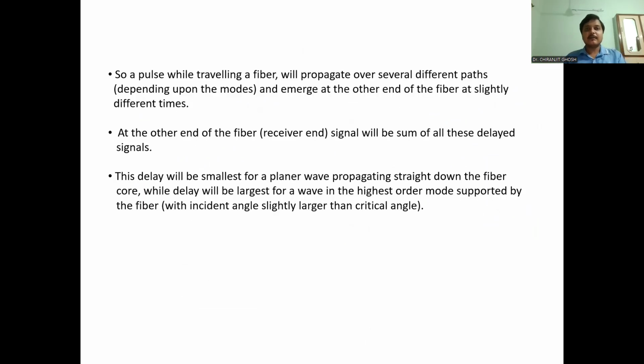Now, ultimately, when they reach the fiber output, it will be a broadened pulse. This is one of the main limitations of fiber optic communication, that is dispersion. Another problem is the non-linear effect, but dispersion is one of the main limitations. So what happens with this intermodal dispersion or multimode dispersion? Because these rays travel at different times, your pulse will be broadened and your bit rate will be reduced. Information carrying capacity will be reduced. So we have to eliminate this dispersion.